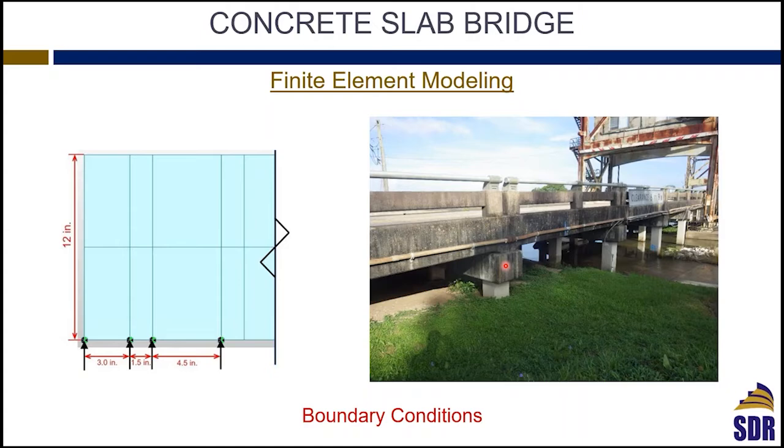But most importantly, you have to make sure that you are preventing the movement along the area of the slab vertically in that direction, since there was no bearing. So this slab was sitting concrete on concrete. So this point cannot move upward or downward because of the bent cap.